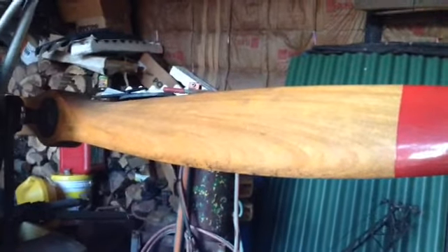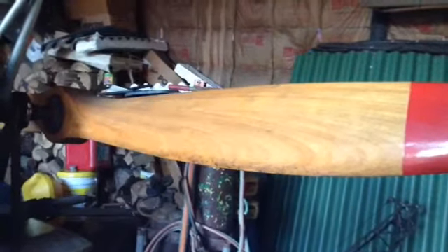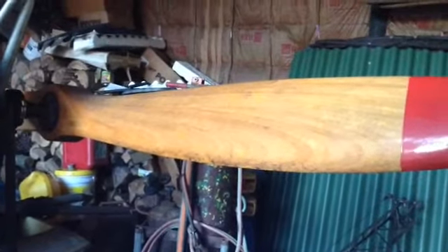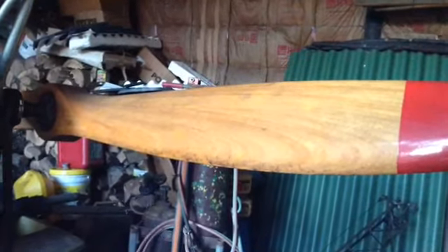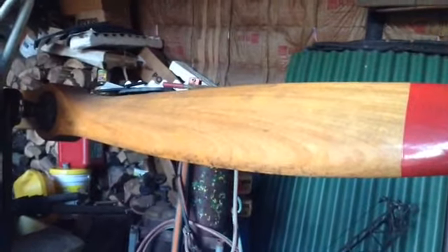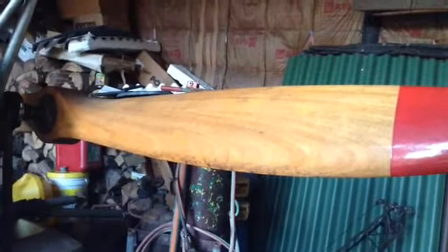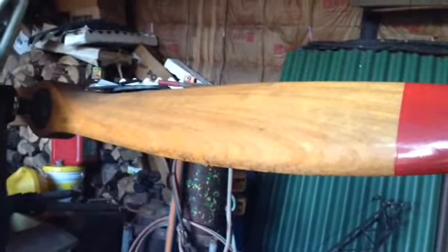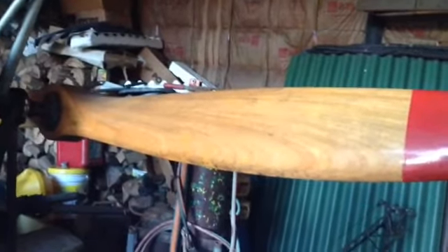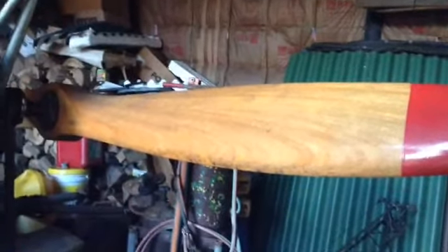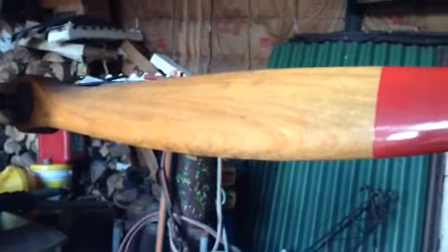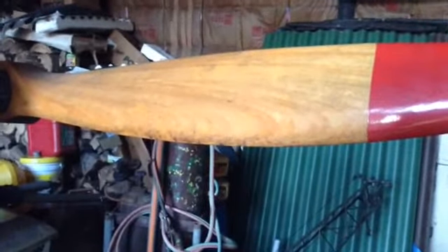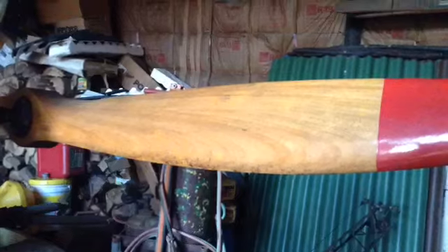Our propeller's mass becomes less going from the center to the tip. Even though the mass toward the tip is less than the mass at the center, this far away mass causes the radius of gyration to be more toward the tip. Remember that the moment of inertia is the sum of all the increments of mass multiplied times the square of their distances from the rotational axis. So the mass that is far away from the axis contributes more toward the moment of inertia than does the mass at the center of the propeller. And the closer a rotational body's mass is to the radius of the body, the closer the radius of gyration is to the body's radius.